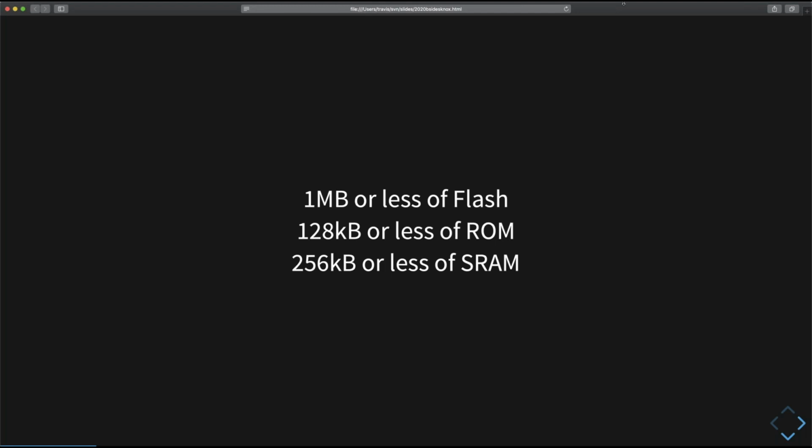And the code can run from SRAM, but it usually runs in place from flash memory. You'll only find it running from SRAM when it's a temporary patch, or when it needs to load a small driver to rewrite flash memory, and for that reason can't be executing from flash memory at the same time.